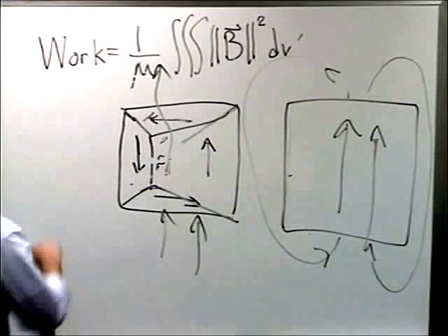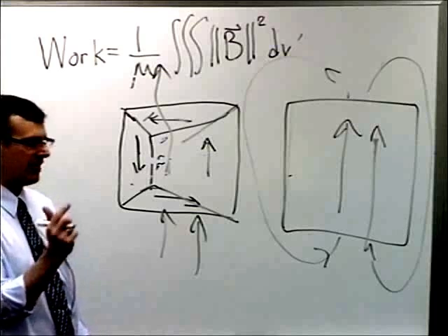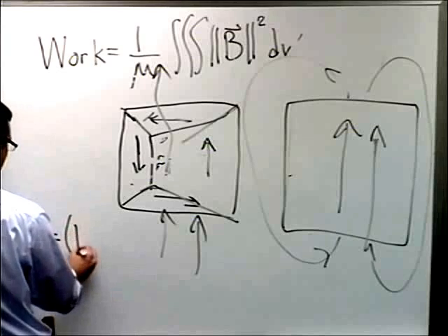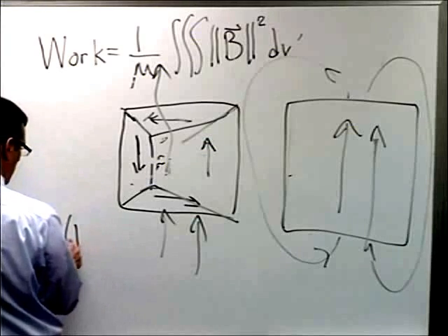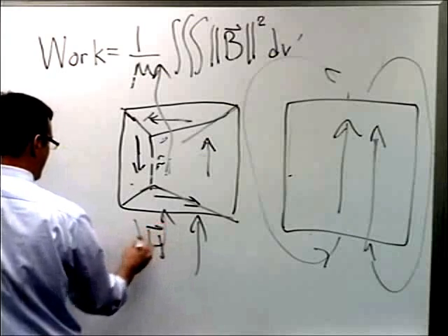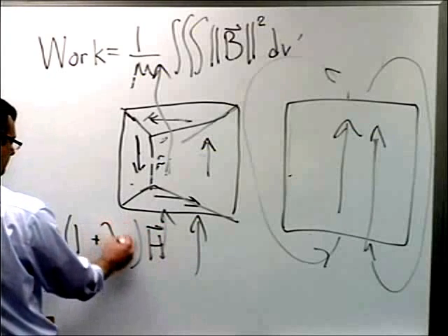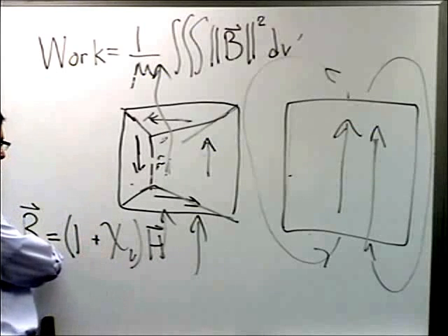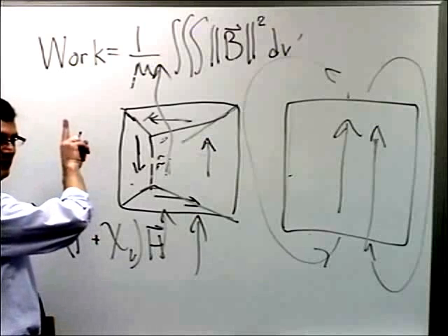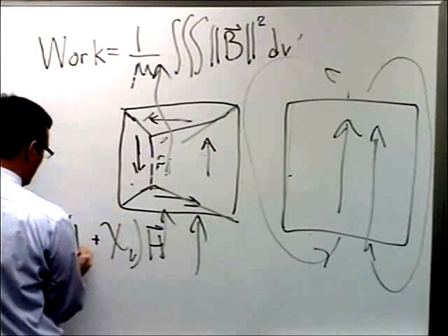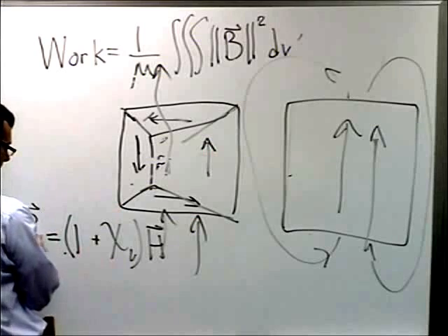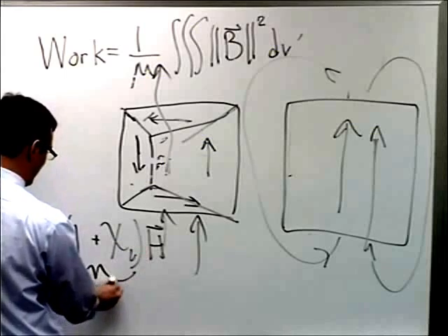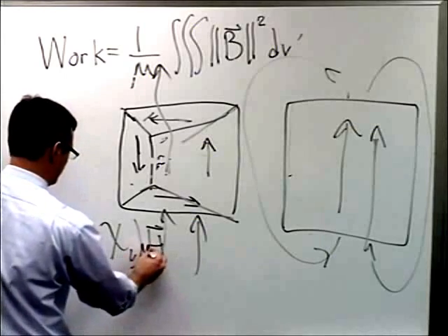Yeah, so the way that we define mu sub r is that you have a B field and you have a corresponding H field, which is mu naught times H. And then if there is any other dipole moment formed by the material itself, sometimes that dipole moment aligns itself with B. Other times, in the case of diamagnetism, it's actually a negative number. So what we do is we impress a magnetic field, we measure the response of the material in terms of H, and we lump those two things together, and we call that mu sub r. There should be a mu naught out here.